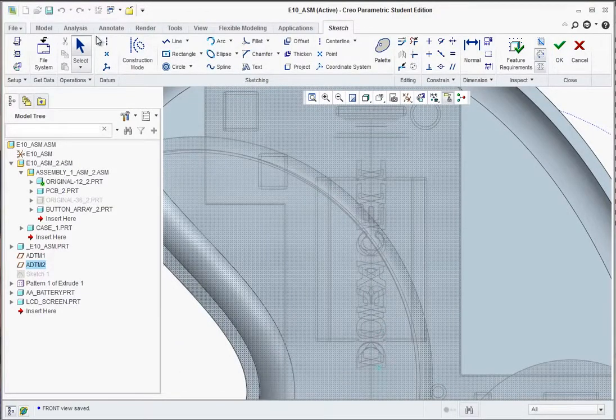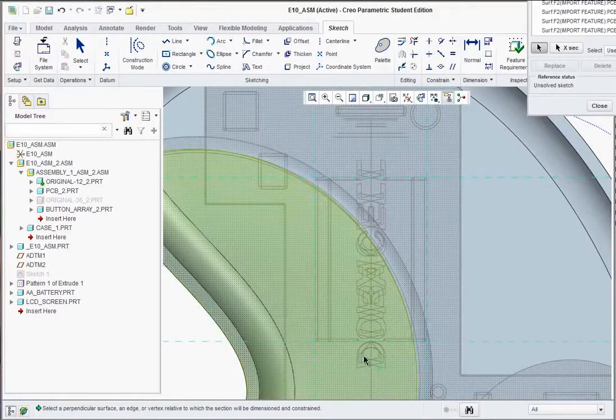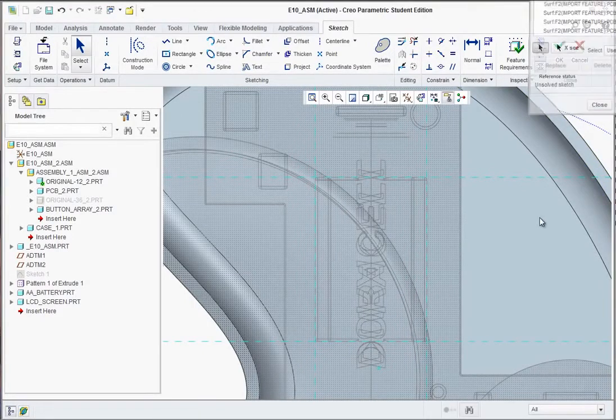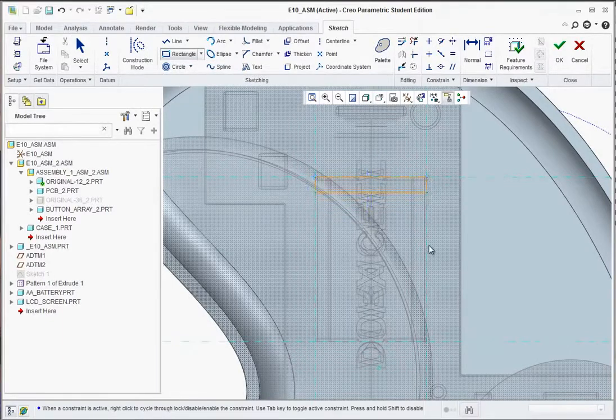So my suggestion here is, first of all, set up some references. So click on references. And then these edges, like click on this edge here, this outer edge here, this one too, and that one. It makes like a rectangle. And you could hit close up here. Okay, now with the rectangle of edges, we can now go to the corner rectangle tool and draw 2 little rectangles. One here from this corner up to this edge, and there. And then just dimension them.